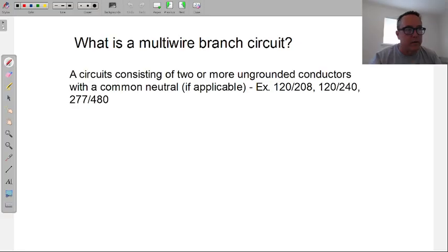Sometimes you need more than 42 spaces. If you get into a commercial building, this is where that rule sort of also comes into play. Because I could have multi-wire branch circuits, I can have two different panels right next to each other, and they don't want one wire and the other wire for a multi-wire branch circuit to come from two different panels. Let's first get into what that is, and maybe that note right now is not making sense, but it will in a second.